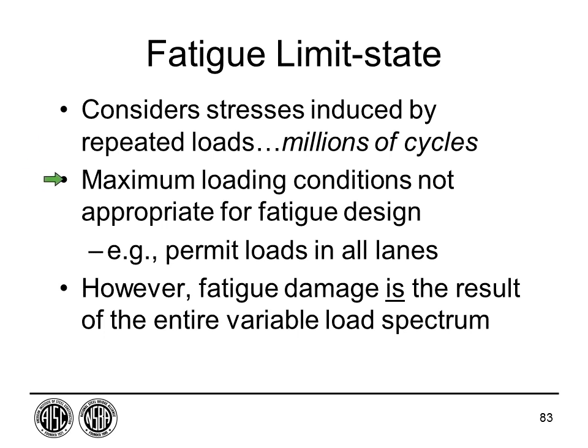The maximum loading isn't what we're worried about. It isn't the heaviest truck that causes fatigue, say permits in all the lanes. It's rather some effect over time. If you go stand along the interstate, well, off the interstate, I don't want anybody getting arrested or hit, but if you go and watch an interstate, you'll notice that there's trucks, but they're not trucks in every lane every time. It's mostly individual vehicles. And some are loaded and some are unloaded, and some are in one lane and then some are in another. It's a highly variable spectrum like we talked about. That's what we worry about for fatigue.